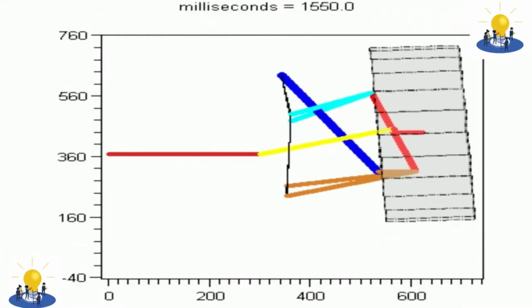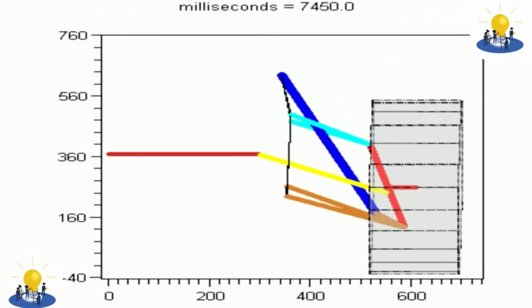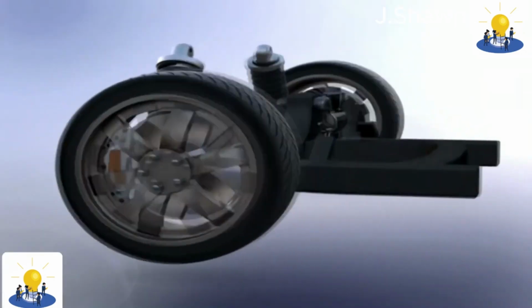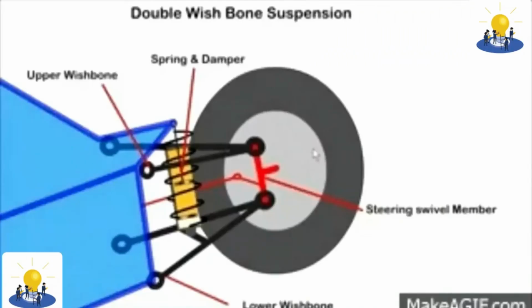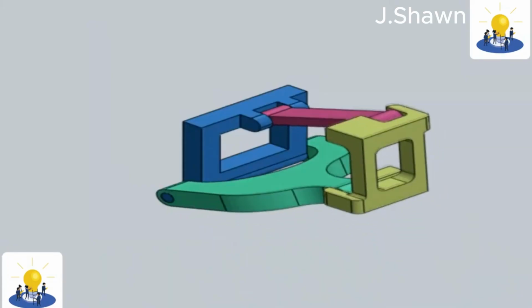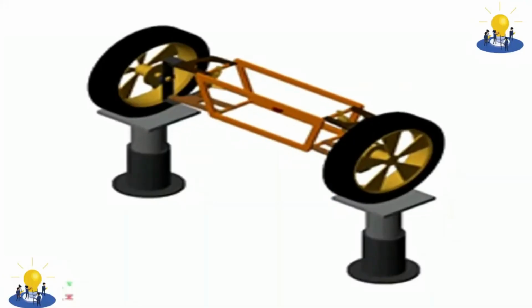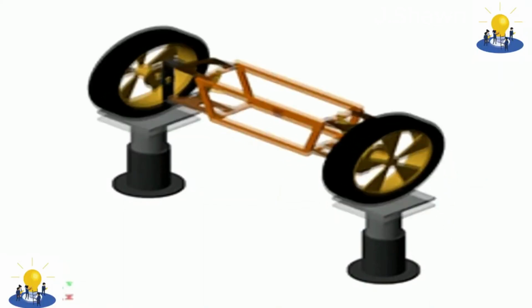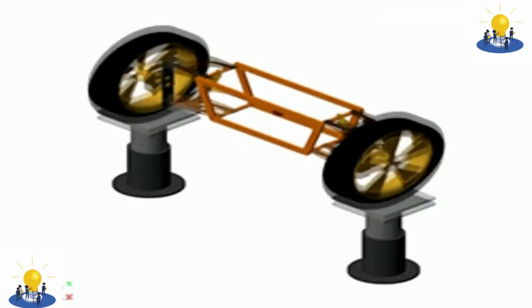In automobiles, a double wishbone suspension is an independent suspension design using two occasionally parallel wishbone-shaped arms to locate the wheel. Each wishbone or arm has two mounting points to the chassis and one joint at the knuckle. The shock absorber and coil spring mount to the wishbones to control vertical movement. Double wishbone designs allow the engineer to carefully control the motion of the wheel throughout suspension travel, controlling such parameters as camber angle, caster angle, toe pattern, roll center height, scrub radius, scuff, and more.